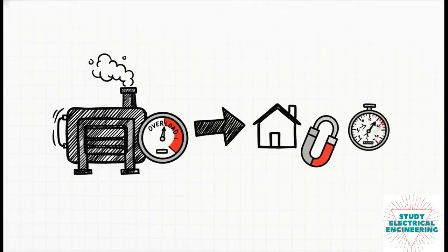But here is a wildly fascinating nuance about real-world physics. Real generators have strict, hard limits on how much reactive power they can pump out or absorb. If a PV bus just doesn't have the reactive power support to hold that voltage and hits its limit, the math dynamically shifts. We literally just treat it as a PQ bus for that specific iteration. We lock the reactive power at its max limit and calculate the new drifting voltage. It is such a brilliant mathematical adaptation to physical reality.